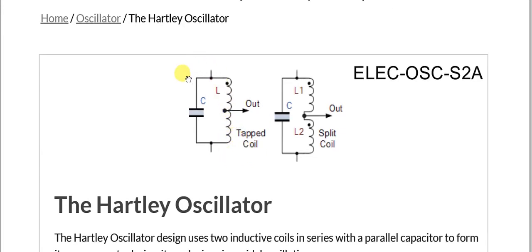So the normal tank circuit, if you remember in the first S1 topic, we defined the oscillator as a device in which the electrical energy oscillates between the L and C. C is charged, then it is discharged through the L, and L is again expanding and collapsing its magnetic field, which in turn produces the induced current, which charges the capacitor again in the alternate polarities.